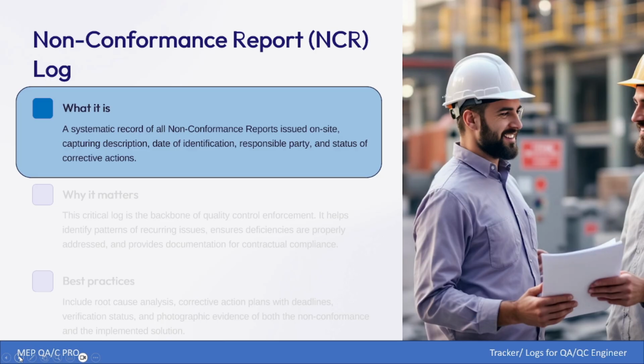A systematic record of all the non-conformance reports you receive on site, capturing the description, date of identification, responsible party, and status of corrective action. So whenever you receive an NCR, at the same time you need to go to your logs, track it down, and mention your NCR number, the description, and, through your knowledge, who will be responsible for that and who will be responsible to close out that NCR.